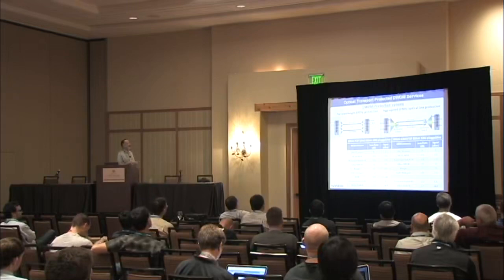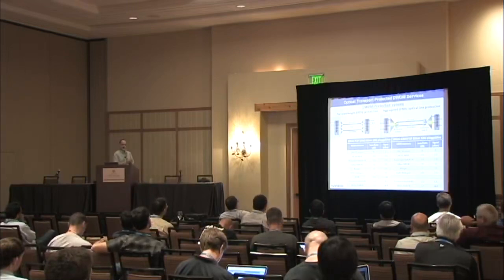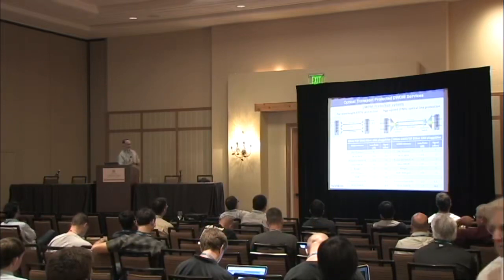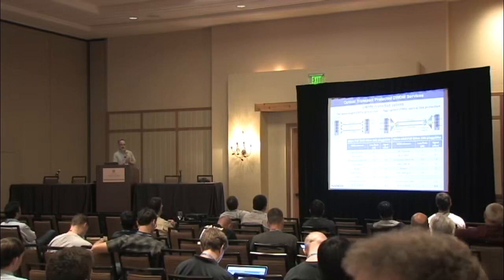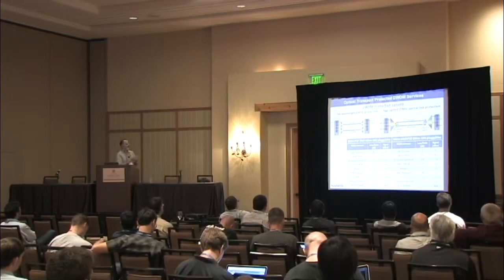The interesting part is when you do optical line protection for the aggregated signal, basically after the Mux Dmax. And this is done by adding a protection switch, and you have a primary and a secondary that switches based on fiber loss or link loss.